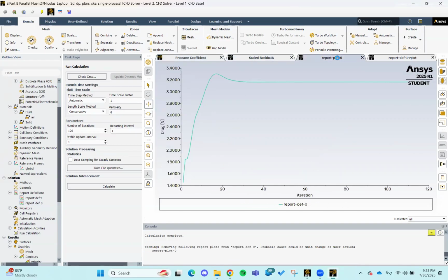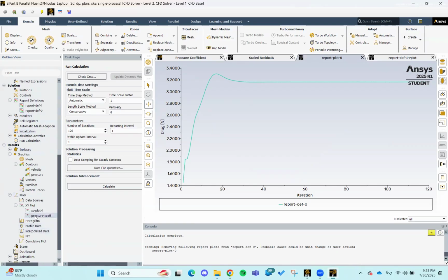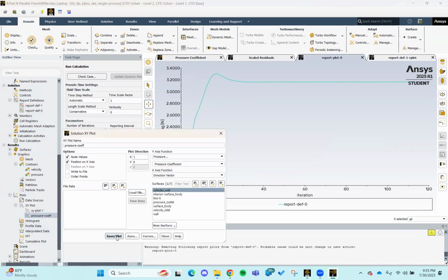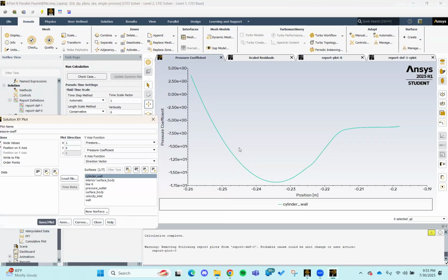Oh, this is my reports. Here you go. But we'll use the drag force and use the formula to solve for drag coefficient of the circle because Fluent won't give us an accurate result, as well as the pressure coefficient distribution plot. Just for the purpose of the video I showed what it gave us in Fluent, but that obviously isn't accurate, because it is using our inlet velocity, but we actually want to use our test velocity.